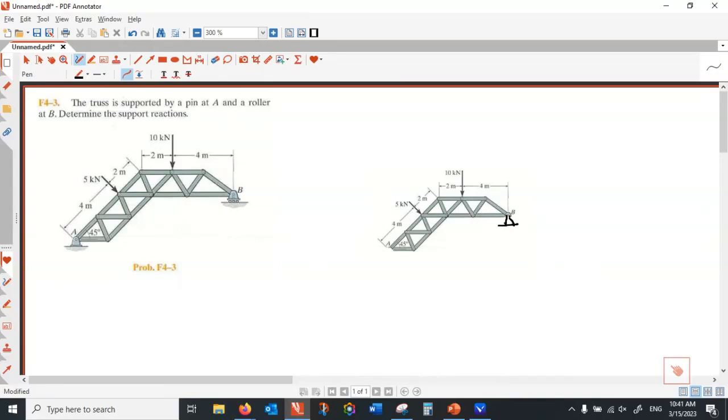Try my best. So I kept that roller head with it. So in this case, I only have to worry about the resistance of the roller against the ground. And what is the direction of that roller to the ground? It's normal to the interface, isn't it? If that roller was going to slide, what was the direction of movement? You have to draw the resistance normal to that movement direction. So that is what you do.